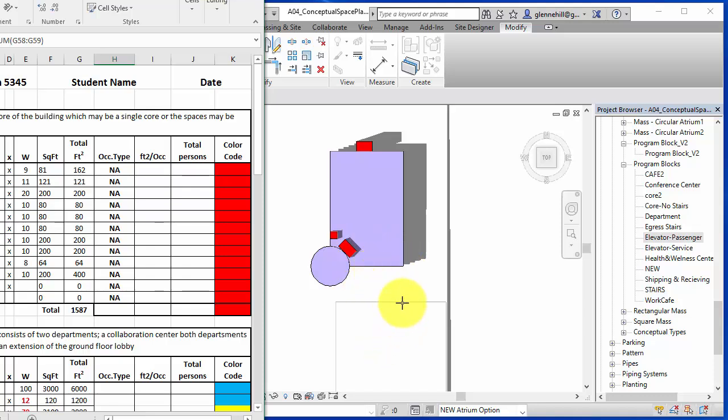Normally you might not do that, but since I have another building right here, none of the views are that great looking at the south side of the building, and we're going to want to shade it anyway most of the time because of the heating. And my views are to the east and the west, and that's the reason I reoriented this. Those are normally the worst case scenarios for climate responsive design, but I've got views I just can't turn down of mountains on both sides of the building, so I've got to orient the building that way to take advantage of it. So I'm going to pop in this service core and then also make up the other elevator.